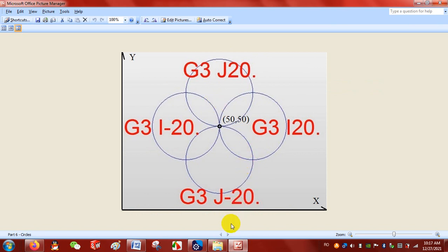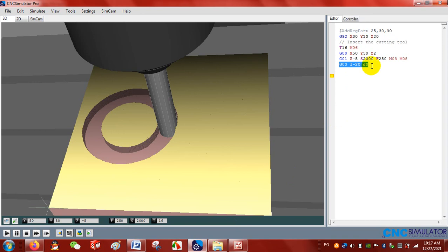So what we're going to do now, we're going to retrieve the cutting tool. I'm going to say here Z5, or Z10 if you like, it's no problem. What value you give here, and we will start making the second circle.